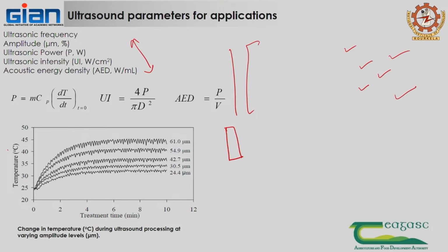They cannot be kept facing each other. Because if you put both, sound pressure comes from here and from there, two different frequencies, it will destroy the transducer. So it has to be in perfect alignment.